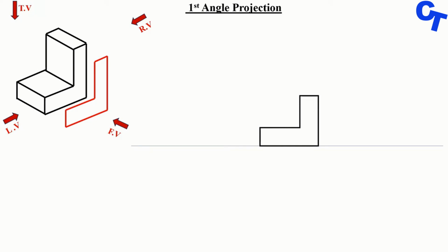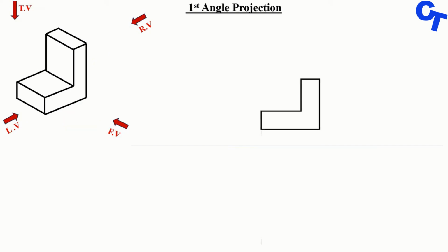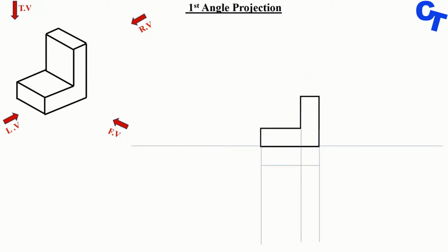On the top line, I'm not going to measure again, since you're given the measurements right here. We're just going to project those lines downwards, from each and every corner. It doesn't matter how many there are, just project them so that you won't measure again. Let's draw this line, which is where we want our top view to start. Normally it's wise to leave a distance of 20 millimeters, not more than 50.